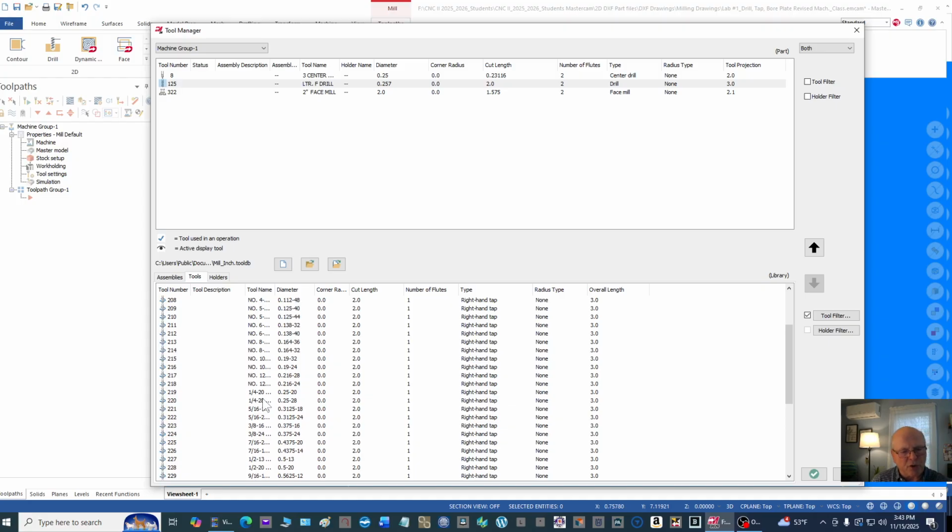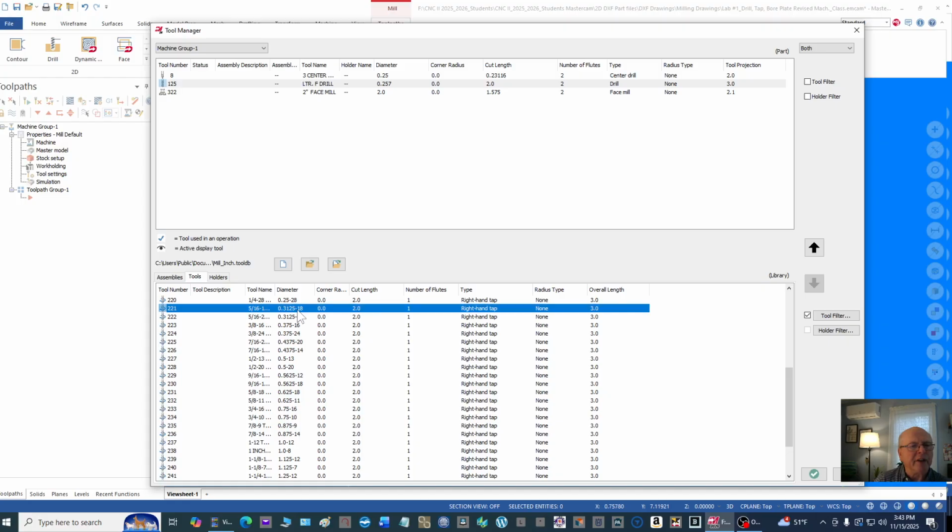Let me just make sure that's correct. Yep, 257 drill, okay. So I'm going to look for a 5/16-18 tap. All right, here's 5/16-18 right here. I'm going to drag that up here and drop that off.